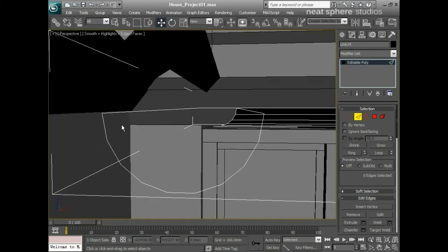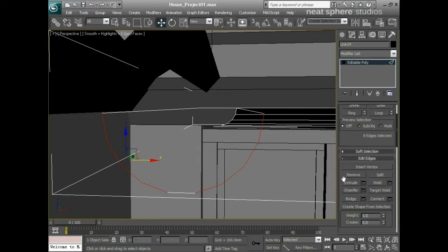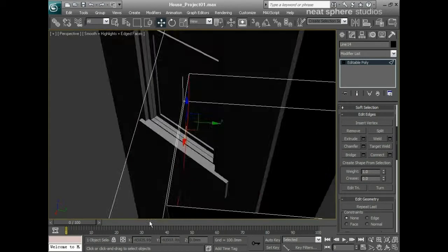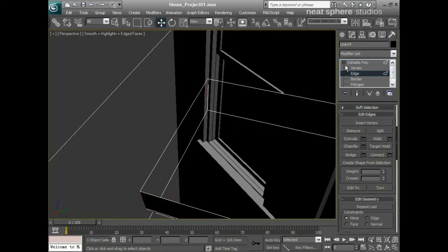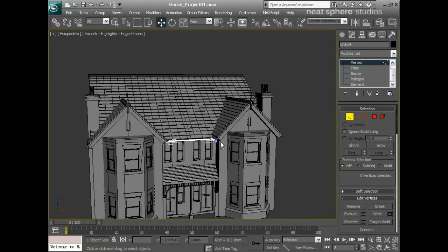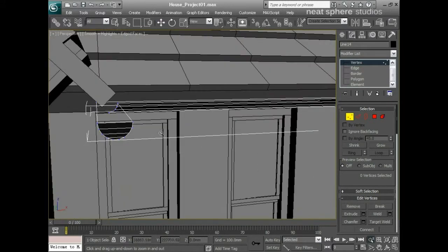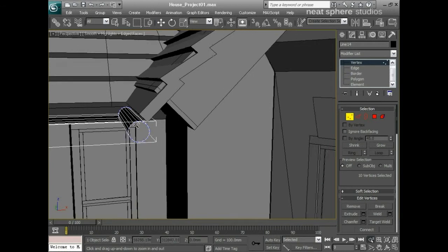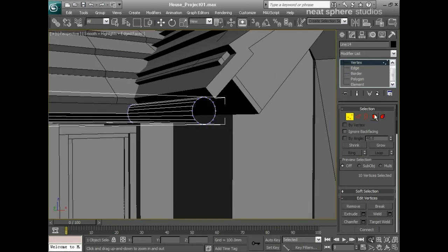And then I'm going to start doing something called bridging. So I'll take these two edges, oops, and these two, and these two, and probably these two. And then I'll bridge. Looks like it's going to work to me. Let's go to vert. Oh, we've lost the object. This happens sometimes with 3D Studio when you're working. Let's just grab all of those and check them for welding. Okie dokie. I'm going to do the same thing over here with the deleting of the faces.